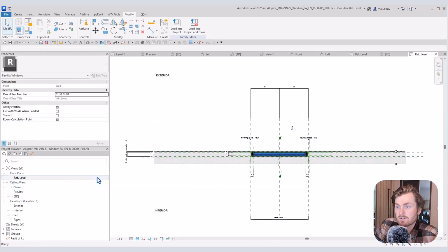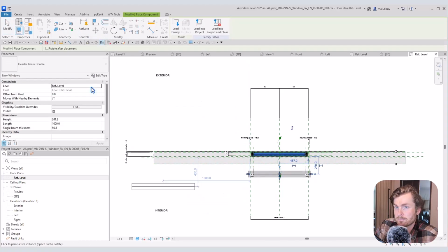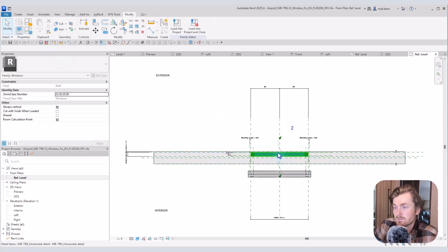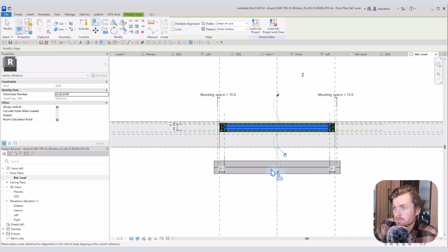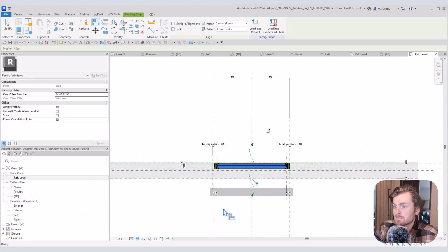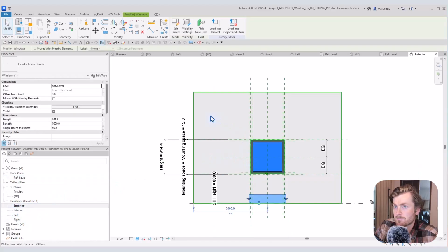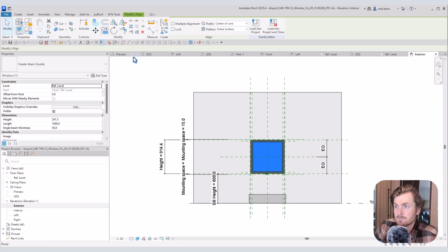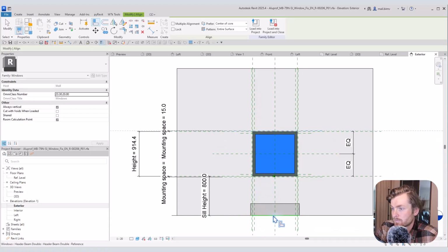Okay, I have to be at the floor and select a component, so I will place it here. Okay, now I should align these objects with Align tool and make sure it's centered with padlocks. It's gonna be on the exterior side, so I will go to exterior and also push it up a little bit. Let's say up to here. I will lock it as well.